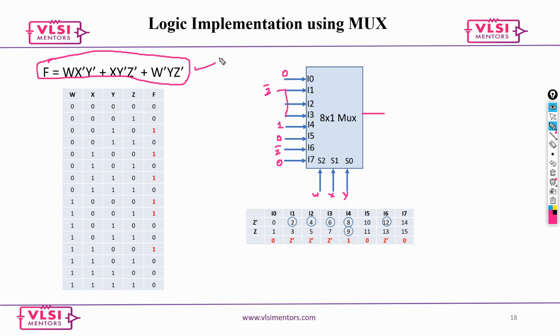But for this, as I said, you need to know writing a truth table and pick the right mux. It is always n minus 1 variables that become the control lines, and then choose the mux having those many control lines, that is basically 8 cross 1.